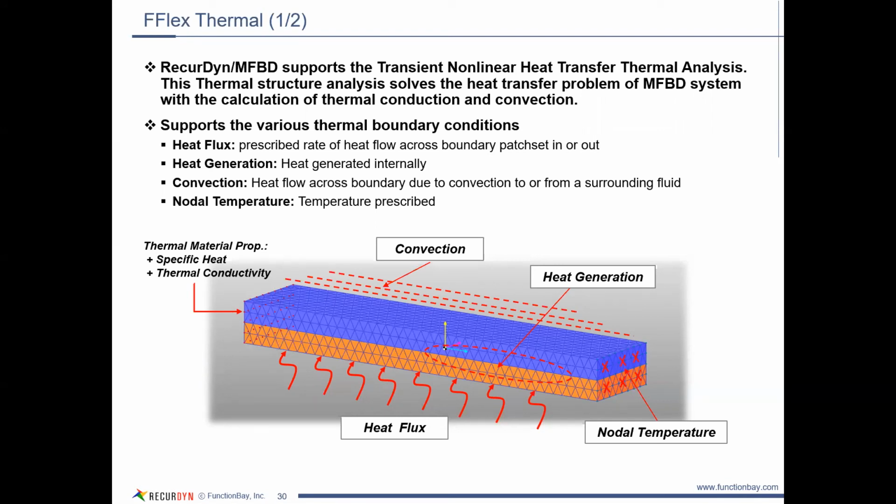As you can see, there are some basic inputs being considered. You can define a heat flux along the surface element faces. The elements themselves have heat transfer properties, and also have the option of defining heat generation within elements. There are nodal temperatures that will result from the heat transfer analysis.